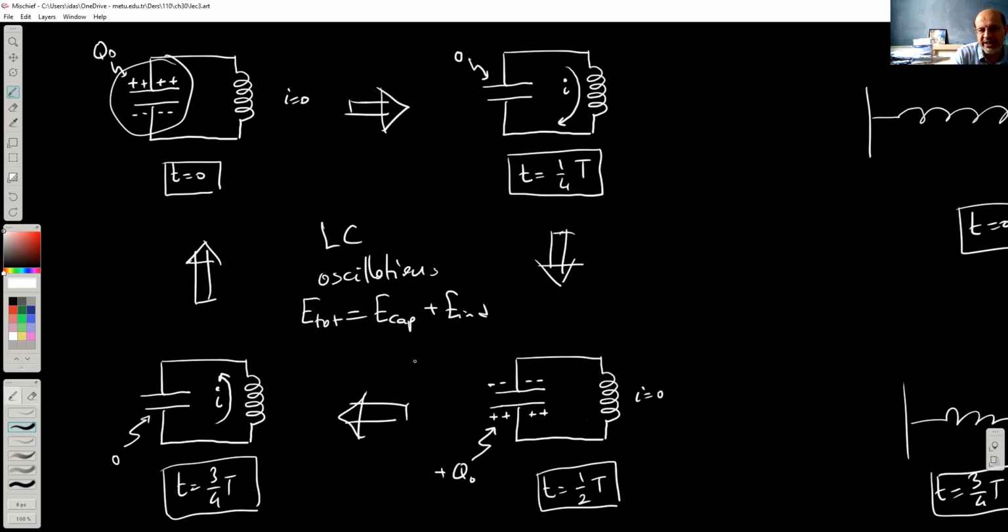But if you make an analog here, the energy of the inductor should be thought of as the kinetic energy because it is associated with something that says that something is changing, right? Something is moving here. Because if the inductor has an energy, there's a current here, and so the charge carriers are moving. So you might think of it like this. That's okay. But just keep in mind that it's not the energy of the charge carriers, right? It's the energy inside the magnetic field.